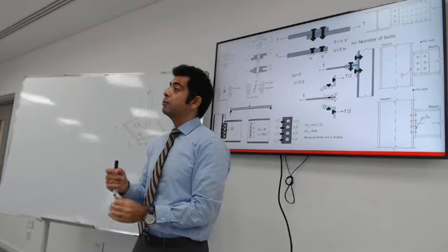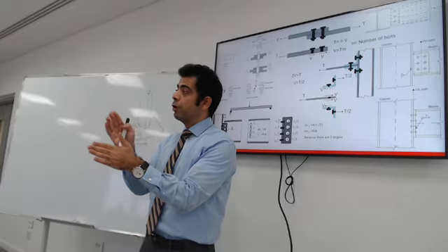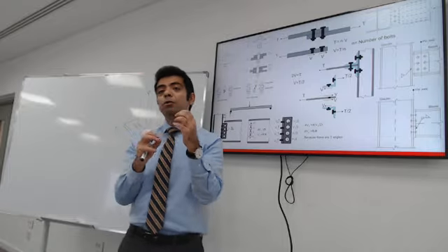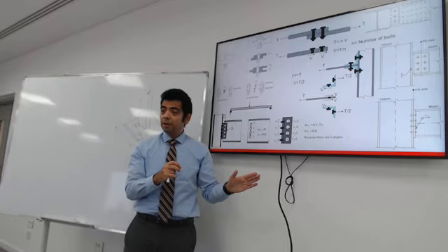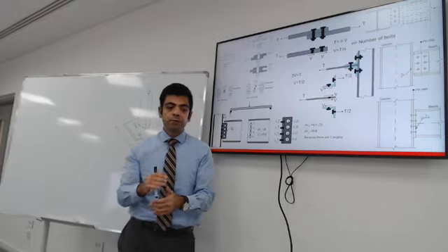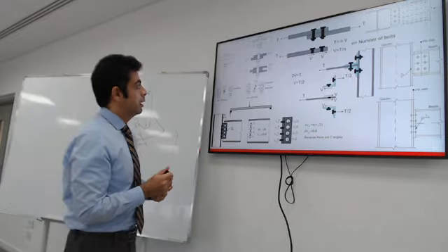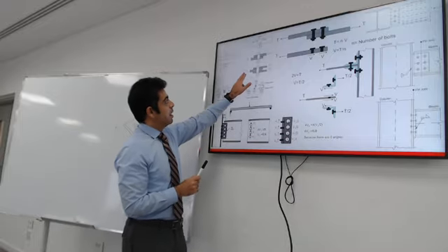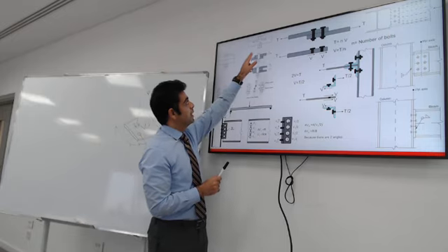Yes, it's the reaction resisted by 4 bolts. And that's how you start analyzing the connection. You want to make sure that the shear on the bolt does not exceed the capacity of the bolt, and you also want to check that the steel beam web is not going to rupture. So those are the 2 checks you need to do. Before I leave that, this is how a bolt can fail in shear, and this is how the bolt can experience tension.